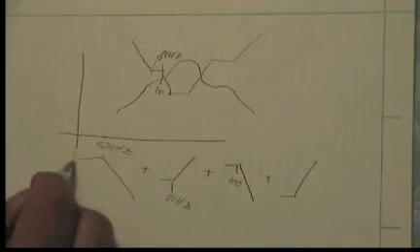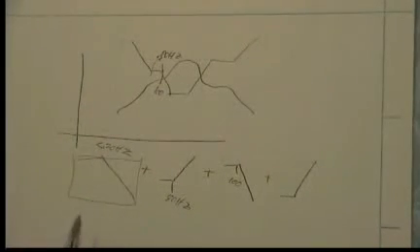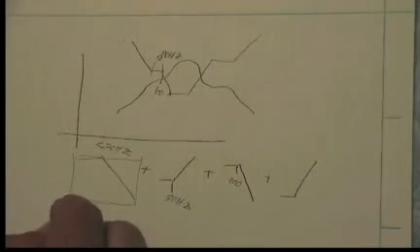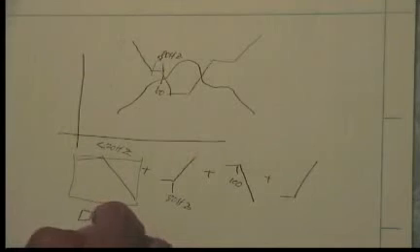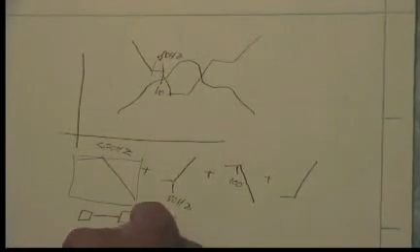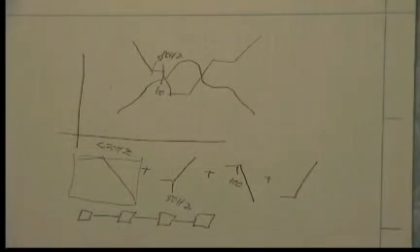Each one of these would be represented by an op-amp circuit, and you look up a design for each of these stages. As I said, like application note 72, you go online and just do a Google search for something like filter design or op-amp filter design, and you'll get lots of different sites that will help you with that.